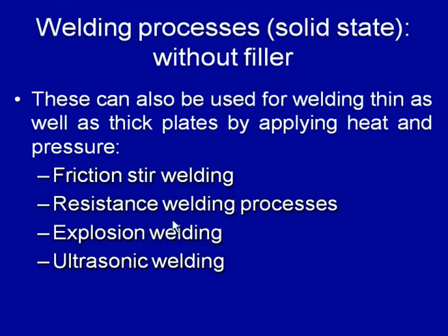And apart from the use of the fusion welding processes, some solid state welding processes like friction welding or friction stir welding process can also be used if solidification cracking is a major problem in case of the fusion welds where filler material is not to be used. Now, we will see the welding processes where filler material is not used, but they are carried out in the solid state without fusion of the faying surfaces.